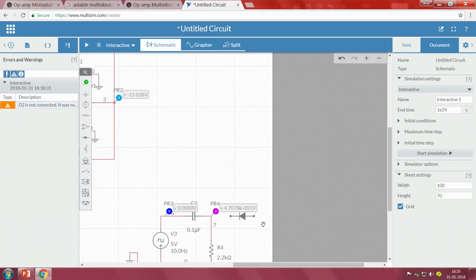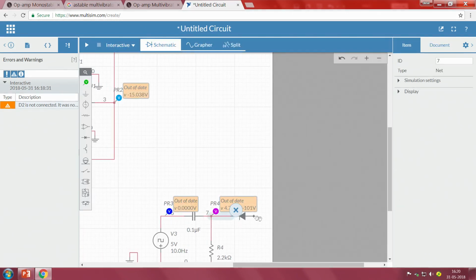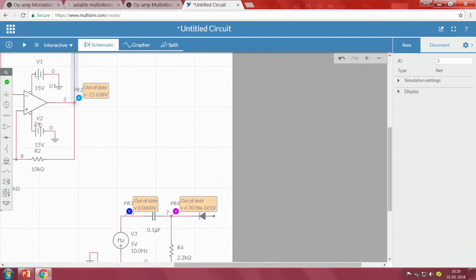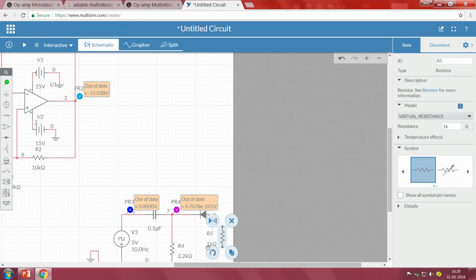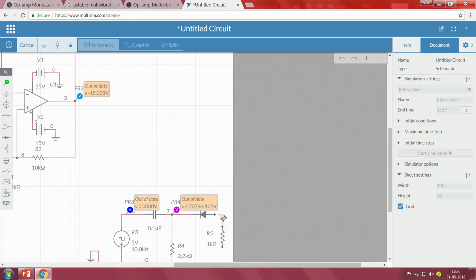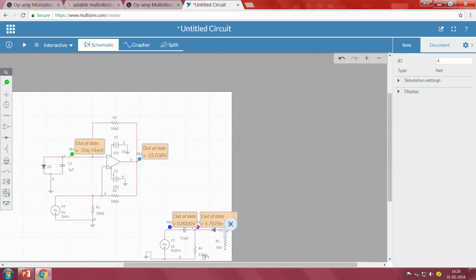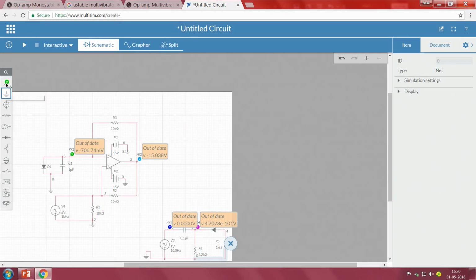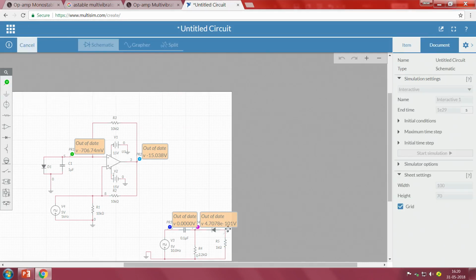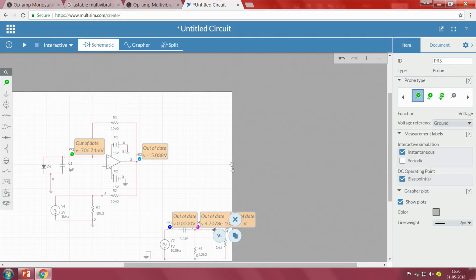One way is, if I use a simple diode, what I will do is connect this particular part to the diode. To visualize this value, we will take one more resistor and connect it across this. I just reverse this, connect this resistor, and connect this particular portion to ground. I will take one more voltage source. So, we will check at this point.